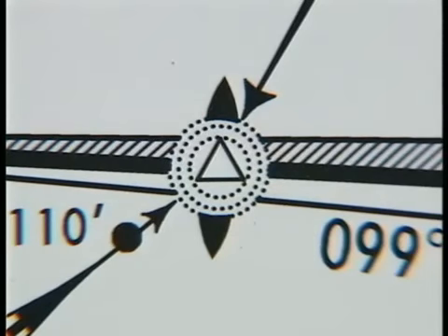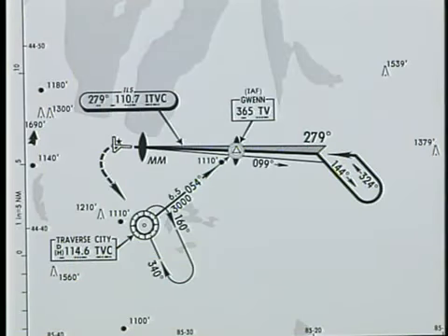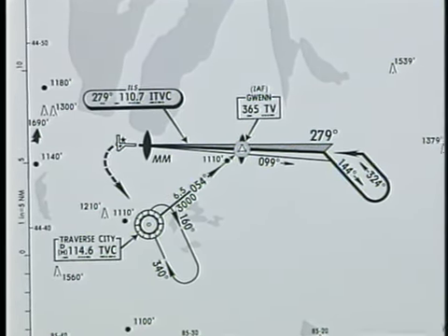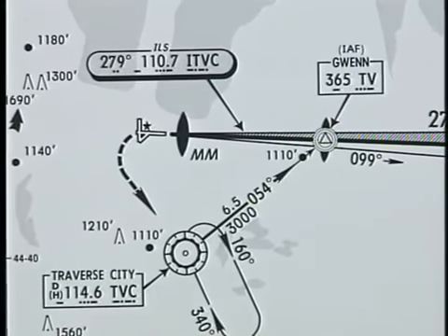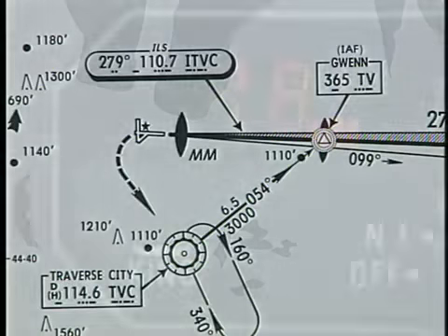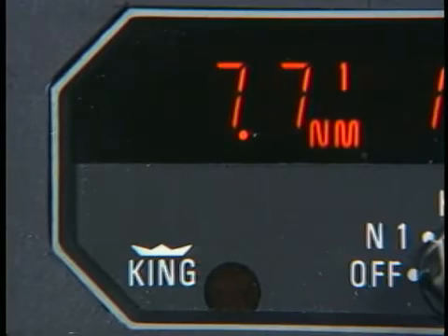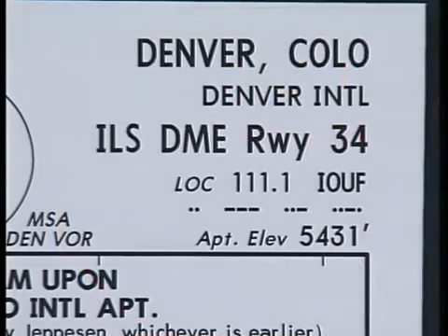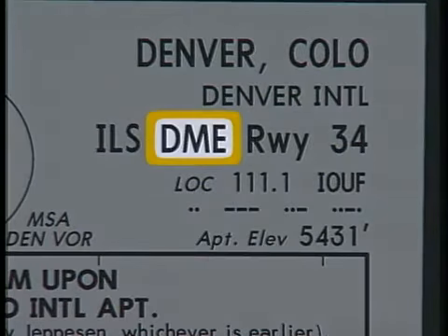Many ILS systems incorporate a compass locator that functions like an NDB to provide additional navigational information. Normally, it is co-located with the outer marker, although it might be placed at the middle marker as well. The compass locator may be used as a nav aid for the transition to the terminal environment or as an additional means of orientation during final approach. Some ILS approaches use DME to help you monitor your distance to the runway, as well as to provide a substitute for some of the ILS components. Where DME is required for the approach, it is indicated in the procedure name.